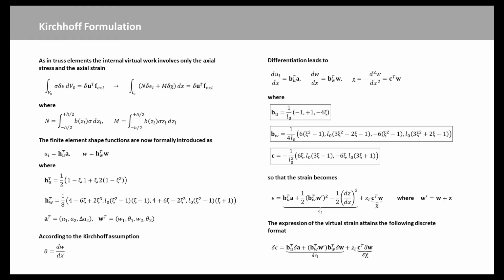Differentiation of the shape functions leads to these equations, and we have a new equation to elaborate the original strain equation, assuming a Bubnov-Galerkin approach. The virtual displacements are interpolated in the same manner as the displacements, and the expression for the virtual strain attains the discrete format.